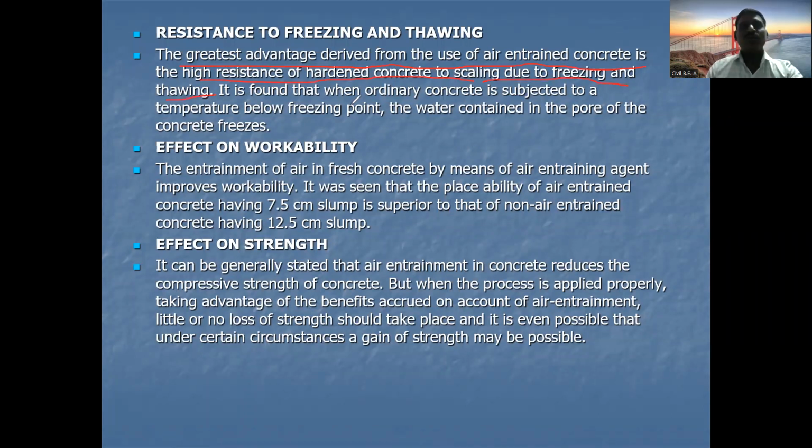It is found that ordinary concrete is subjected to temperatures below freezing point, and the water contained in the pores of the concrete freezes. So resistance to freezing and thawing is one of the greater advantages of using air entrained concrete, giving high resistance of the hardened concrete to freezing and thawing.